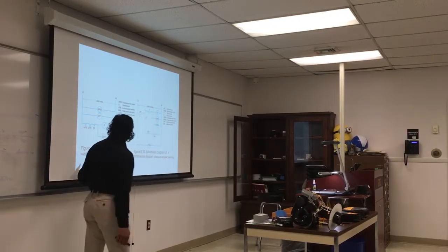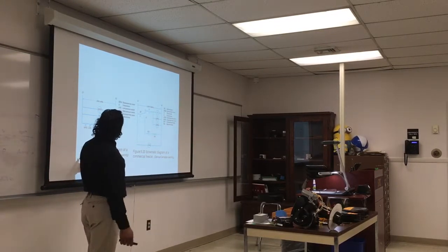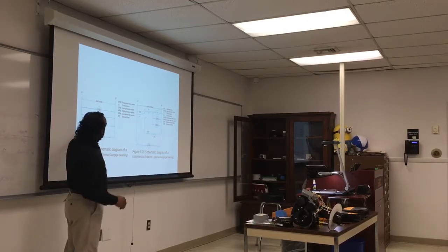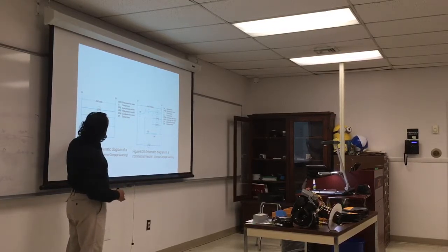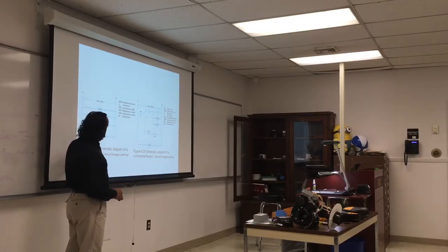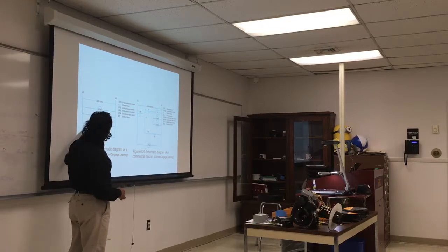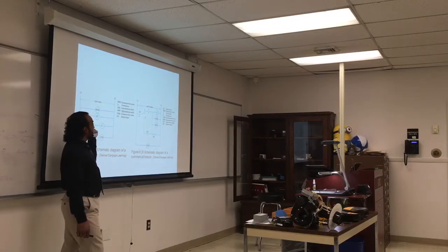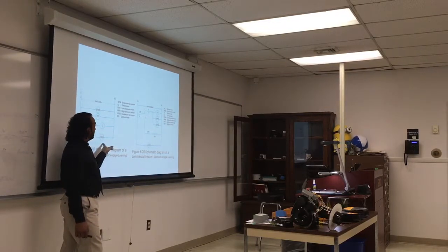Let's look at this. Walk-in cooler, same idea. Evaporator, fan motor, defrost timer, compressor, and condenser fan motor, and these are controls which are in series or parallel. Series, and these are all in parallel.